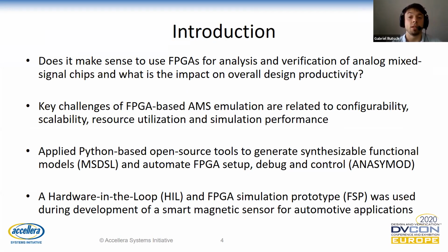Some of the key challenges that we had to address when we entered the mixed signal emulation domain was, on the one hand, configurability. Compared to a CPU-based simulation platform, you need to make sure that parameters are runtime configurable. If they are not, then you have to synthesize again every time you change a certain parameter setting.